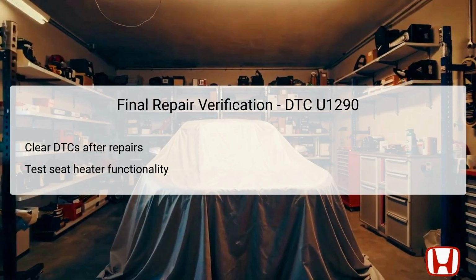Following this, test the functionality of the seat heater by activating it through the climate control unit to confirm communication is re-established and the unit operates as intended. Observing proper activation without any DTC reappearing validates that the repairs were successful. This step ensures your vehicle operates at full capacity without lingering issues. Maintaining a record of repairs and system checks can also be beneficial for future reference.